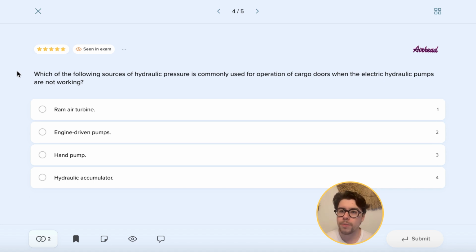Of course, for the Airbus, there is an electric pump for the yellow system, and this will allow us to pressurize the system even though the engines are not running. However, the cargo doors will also have a manual way of pressurizing this system, so the personnel can do this relatively on their own, without the need of any major systems being turned on or the help of pilots, as it is in this case.